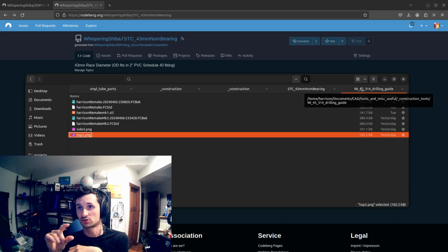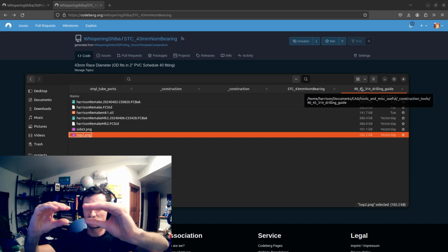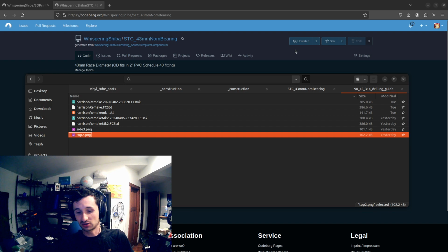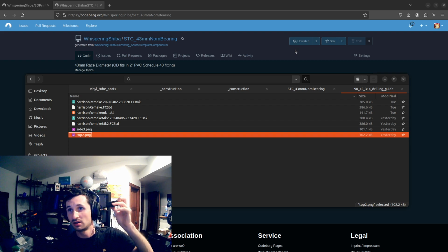Standard 1.5 inch actual dimension, like a 2x4 or a 2x10 or whatever you have. If you have the short dimension like this and you're butting it against another board like this, and then you put a screw in at the 45-degree angle, you're going to pop out the other side with your 2.5 inch screw. So I decided to make another drill guide with a 31.4 degree angle for everyone to use.